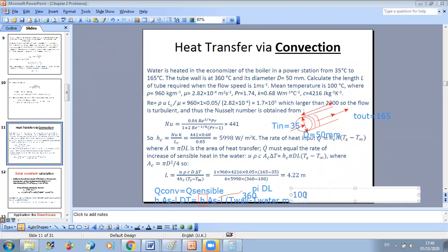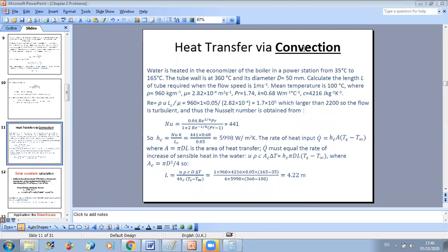So now I still need to find the expression of H. From here, if you remember, in the course material, we said the importance of dealing with non-dimensional numbers. Okay, so you have Reynolds, Nusselt, Prandtl. Why do we use these numbers? Because we can come up with general empirical relations that can be extrapolated to a general problem too.